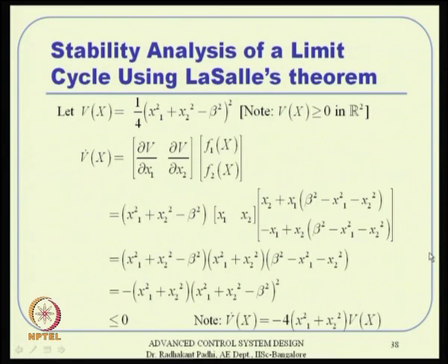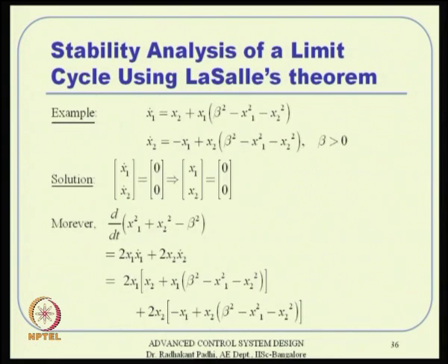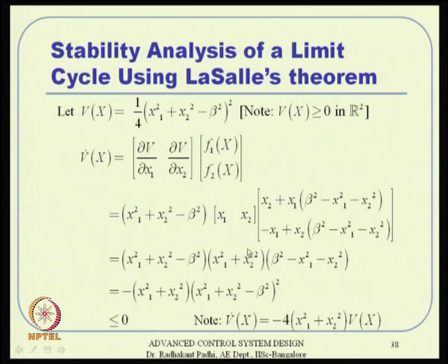Now, we will go back to this Lyapunov function and try to see what is going on there. So far we have not started with any Lyapunov function, we just simply analyzed this expression. Now, let us start with a Lyapunov function; I will take the same expression with a whole square term. Obviously, this happens to be positive semi definite in R square.